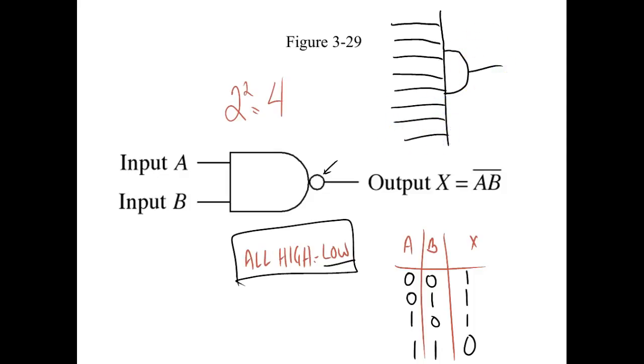Now, how many input combinations would this have in a truth table? It'd be 2 to the 8, which is 256. So you think I'm going to do a truth table for that? No. But what does it say? It says all highs to get low. So if I came over here and put that right there, the output would be low, because I don't have all highs. So if any input is low, the output would be...